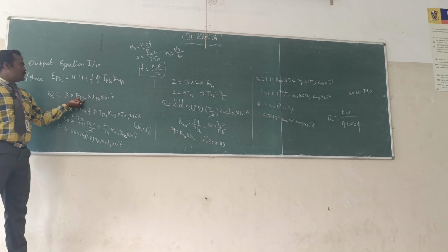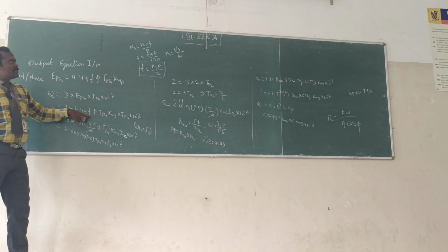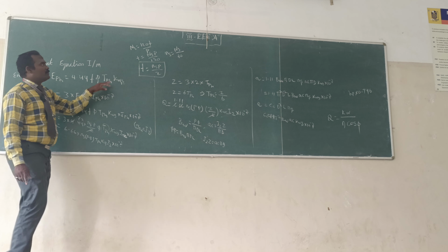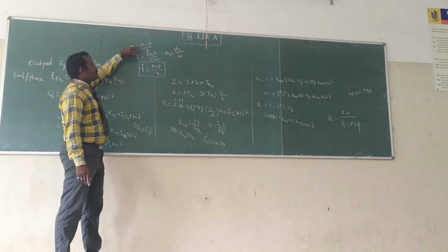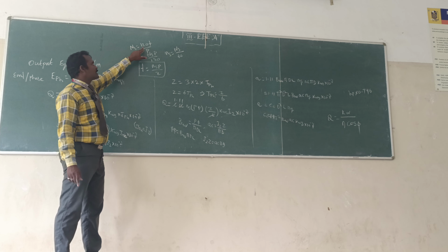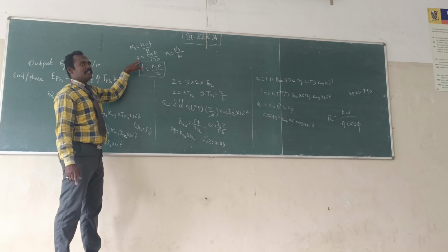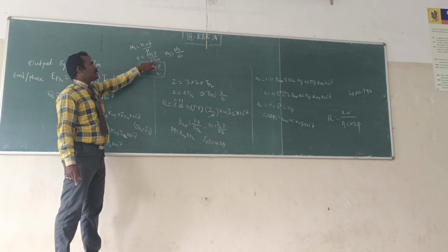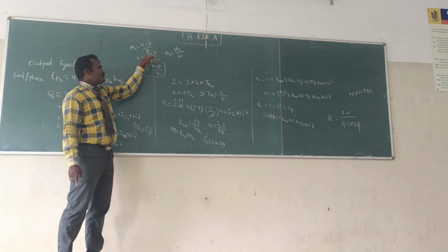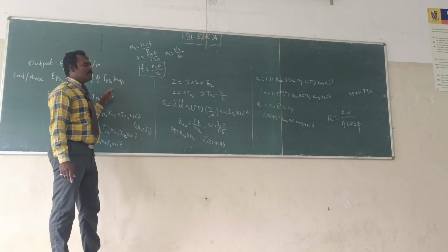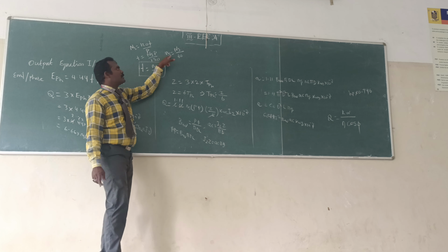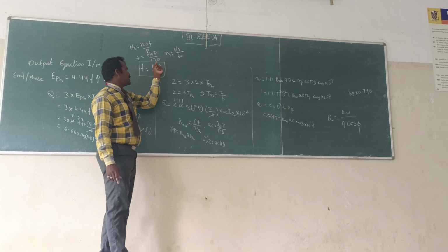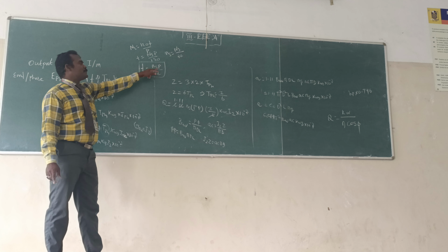So you can substitute the EMF equation in this expression, then simplify it. The frequency f we can find from the synchronous speed expression, that is Ns equals 120 f by P. So from that f equals capital Ns P divided by 120. We always consider the speed in RPS, so Ns in RPS equals synchronous speed divided by 60. From that, f equals Ns P divided by 2.